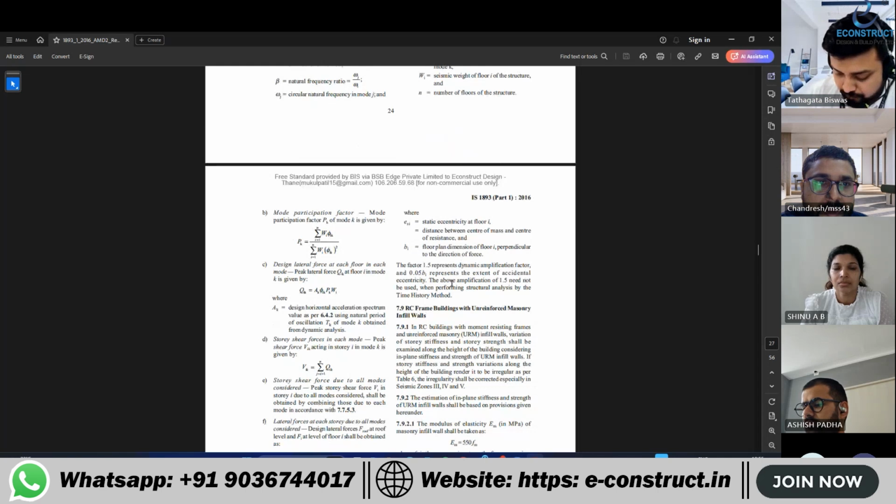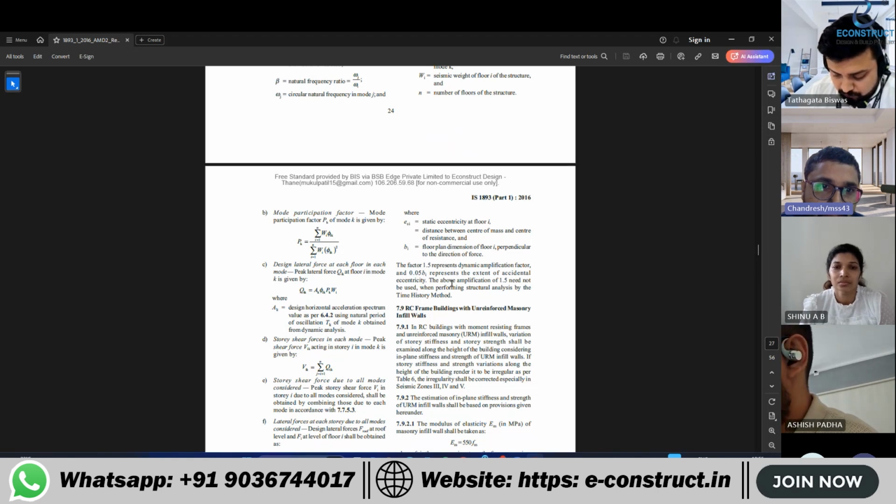Okay, sir. So B, modal participation factor. Modal participation factor Pk of mode k is given by this. C. Design lateral force at each floor in each mode.